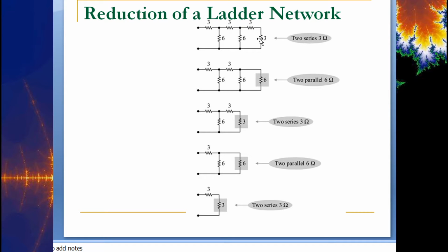So if we were to rewrite this with an equivalent 6 ohms resistance here, now I take this branch in parallel with this branch. Well, anything in parallel with itself, you divide it by 2, right? So 6 in parallel with 6 is 3. Okay, so right there, these 2 got reduced down to a single resistor, right? As if there were just a 3 ohm resistor here.